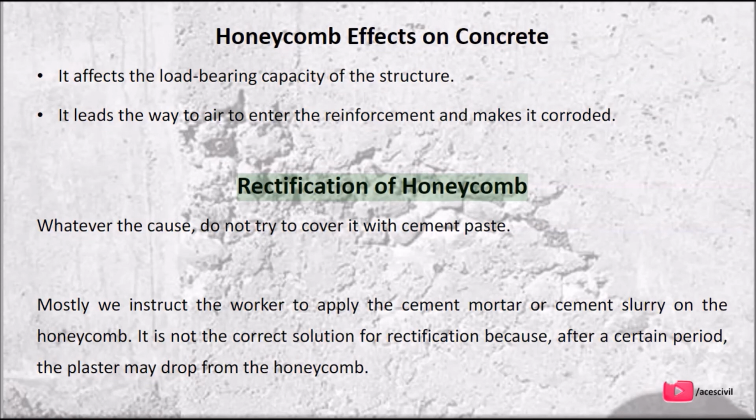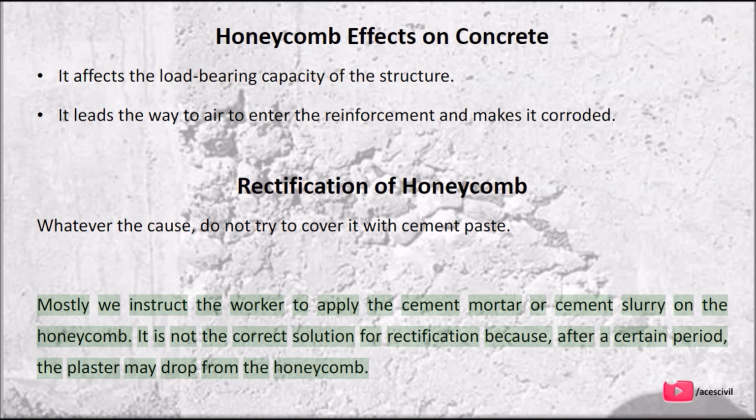Rectification of honeycomb. Whatever the cause, do not try to cover it with cement paste. Mostly we instruct the worker to apply cement mortar or cement slurry on the honeycomb. It is not the correct solution for rectification because, after a certain period, the plaster may drop from the honeycomb.